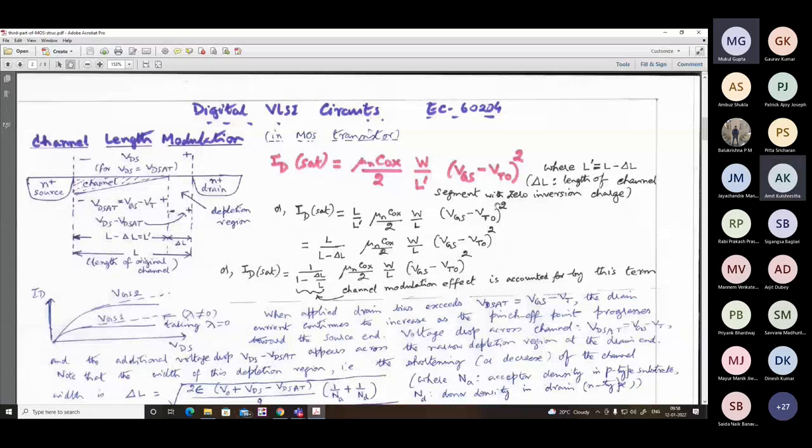Let us assume that, because on the circuit designer side, we cannot go deep into the device physics. You would have to consider several statistics like Maxwell-Boltzmann statistics, Fermi-Dirac statistics, Bose-Einstein statistics, all these things, then the concept of density of states. I lose track of that actually. So let us tacitly assume that for degenerate p-type semiconductor, EV and EF will be coincident, whereas for degenerate n-type semiconductor, EC and EF will be coincident. That will make the calculation easier.